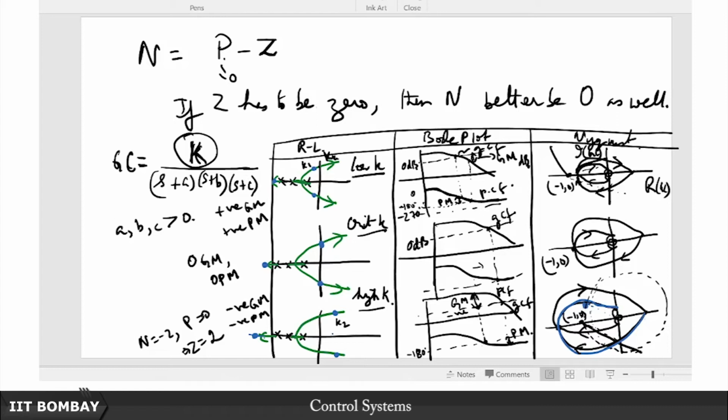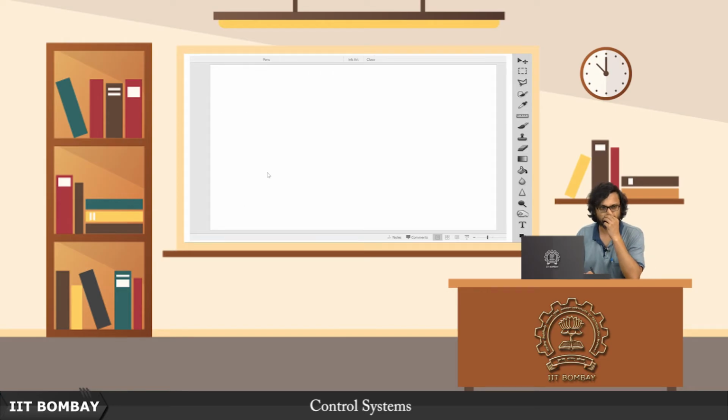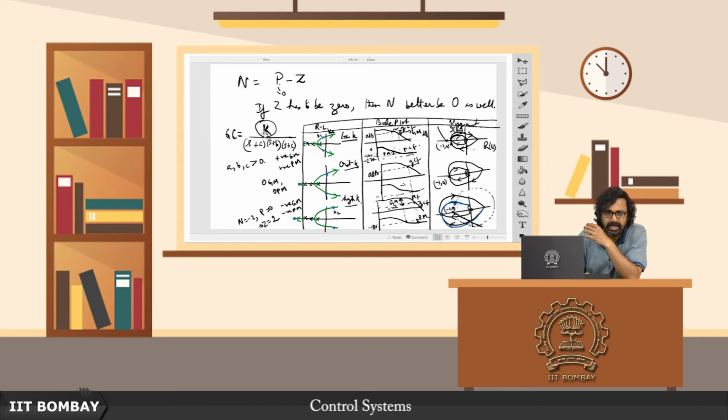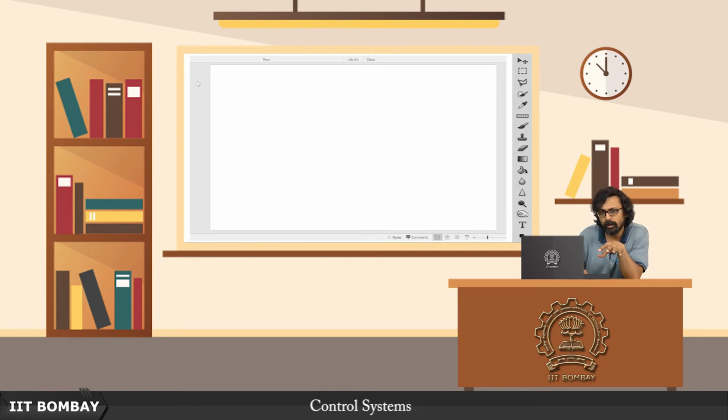But I would say that the picture of all of this we have drawn and the way we understood will remain incomplete unless we discuss one crucial aspect. So let me take this final case. Since we have just talked about varying this gain k, which is basically changing the magnitude plot, there is also a way to change the phase plot alone without affecting the magnitude plot, and we have already seen one way of doing that, that is adding a delay term. But apart from a delay term, there is also another way of doing it.